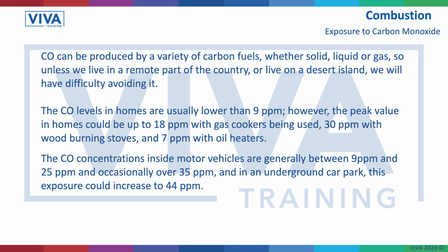The other one is short-term exposure to high levels. So the gas fire where the crows built the nest on the top of it, we're going to get high levels of carbon monoxide. Potentially, if it's so high, 2 or 3 minutes in that room, and we could start feeling the effects. And the effects, depending on the level, as we'll see later on, could start off at feeling a little bit poorly, resulting in fitting and ultimately death.